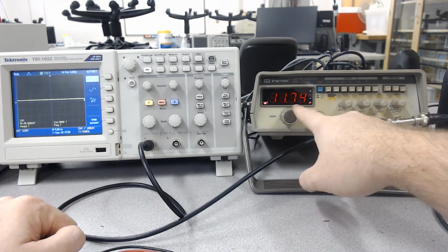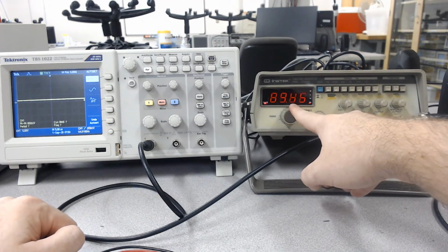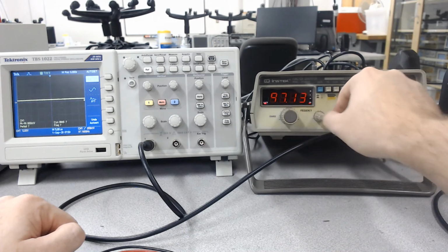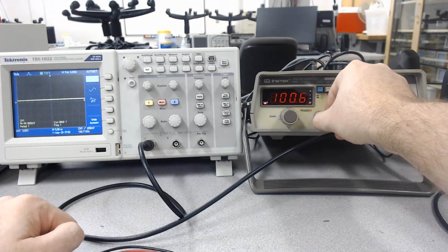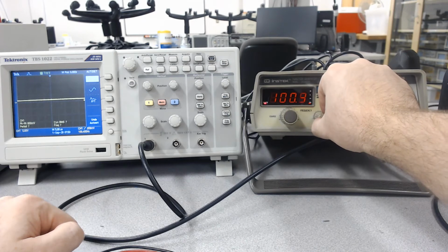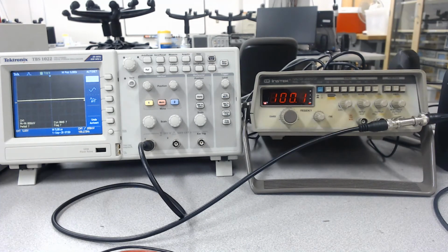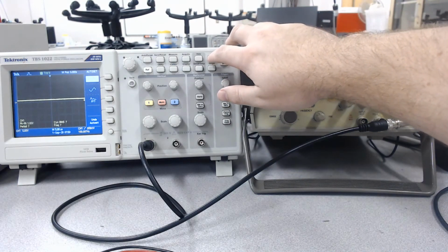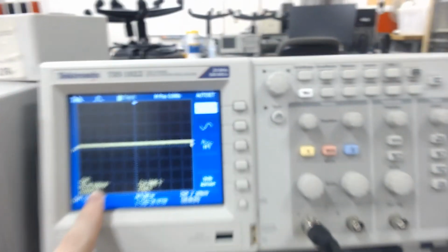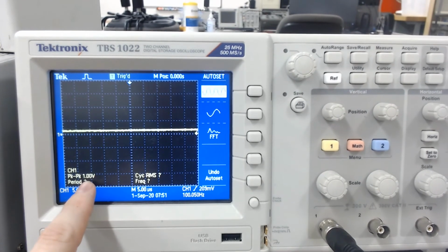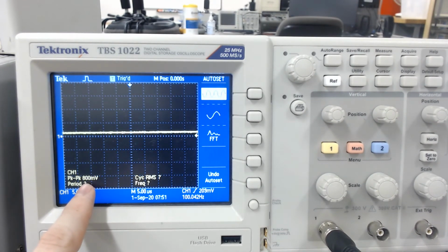We're only at 11 hertz right now, so now we can use this coarse knob to change it up. And for the fine knob, to get it a little bit more exact, we can slowly twist it so that we get roughly 100 hertz. I'm not going to worry about that last 0.2. Actually, it's 0.1. Again, the oscilloscope isn't really showing, and I can't read too much on that. Before I hit the auto set button, it's very important to note that this is changing. I'll zoom in for you. This is changing between 800 millivolts and 1 volt, which seems like a pretty big percent error.